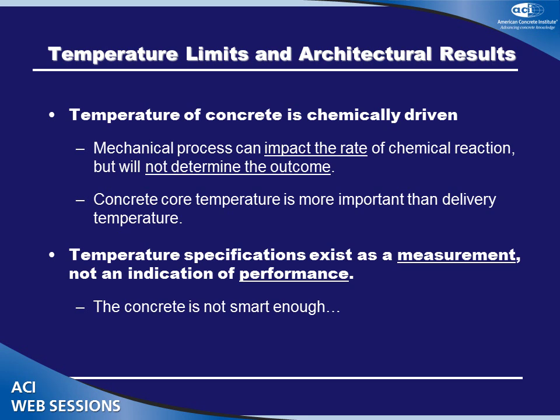The other thing is, I've always been in this situation where somebody said, well, you placed that concrete at 102 degrees. It was too hot. Look at this. We're looking at the lab reports right here. 102 degrees, you placed concrete. It was too hot. We had a 90-degree limit on this. Well, I want this concrete torn out. Well, what was the spec on the concrete? Well, it was 4,000 psi. Well, what did the cylinders break? Well, in 7 days, they broke at 5,200. But it was too hot at placement. Well, do you want to tear it out for that? In my experience now, going on 20 years, I have yet to be in a situation where we've torn out concrete because it made strength but was too hot.